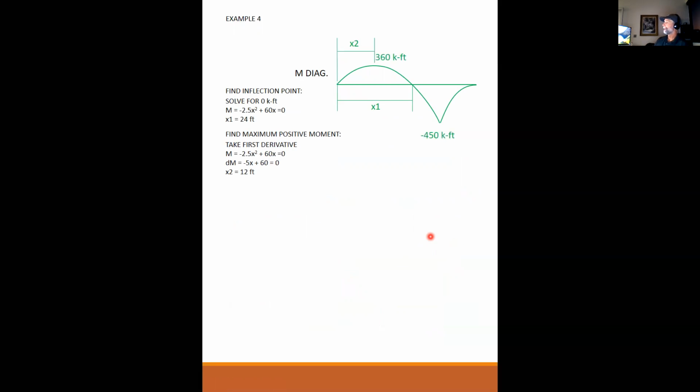And then that second equation, if I plug in 40 feet, then I had better get 0 because this end has to be equal to 0. That's the free end of the cantilever. There was no applied moments and no means of rotational restraint. So this has to equal 0.